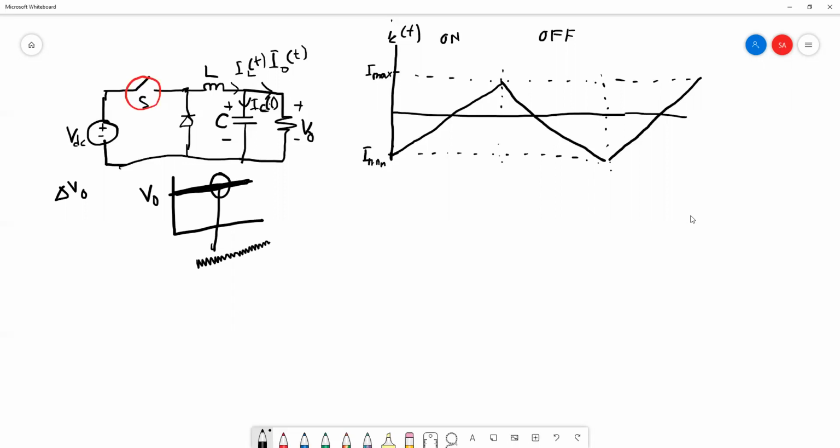Okay, so this is actually the ripple that we refer to. The smaller the ripple, the better the DC-DC converter. But it is a very challenging design, because to meet the design criteria, some of the values need to be considered in great detail. In this ripple output voltage, the component that will affect this value is the capacitor. So we want to see what the equation of this capacitor is in relation to the ripple output voltage.